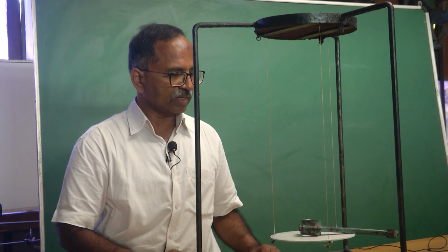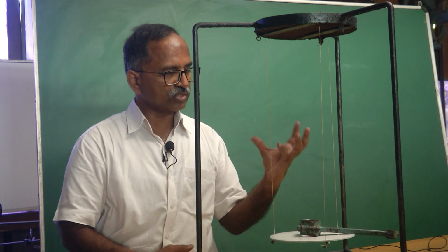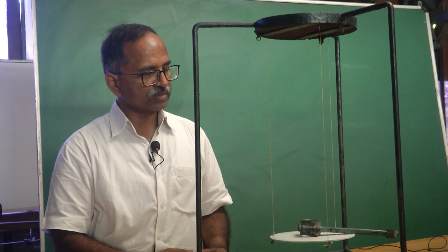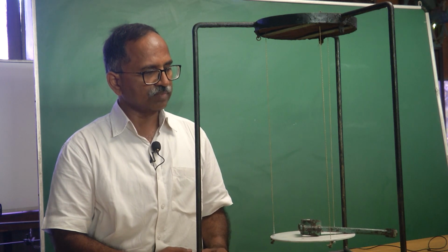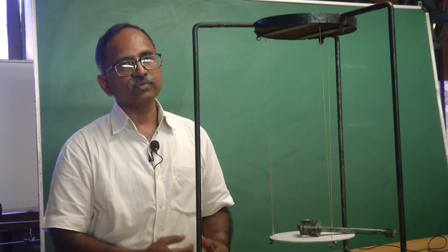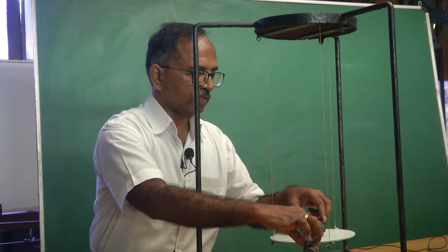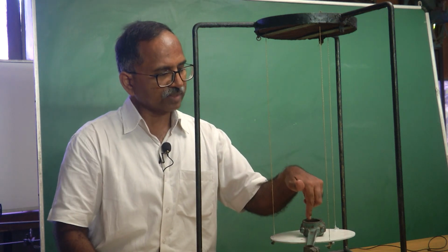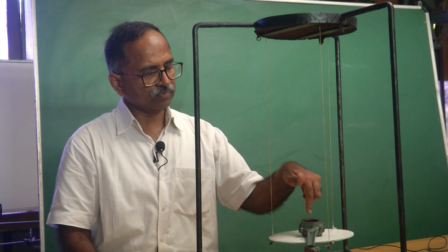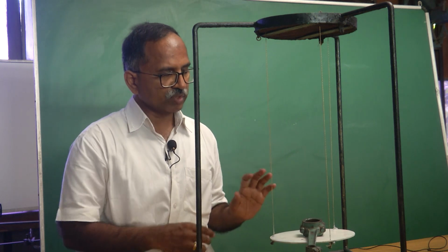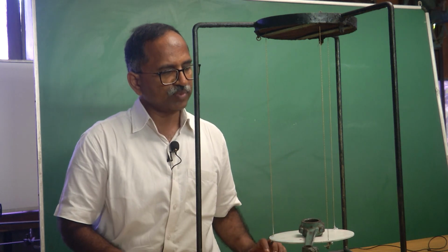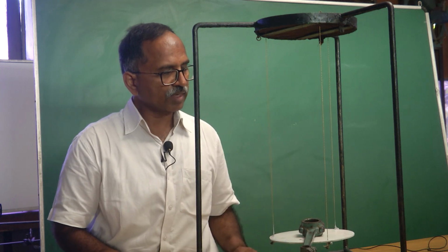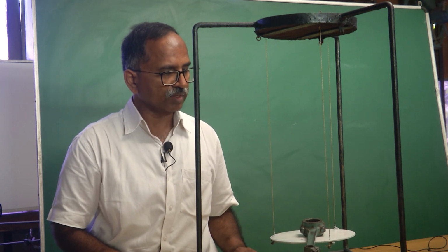And you can notice that the plate is generating an oscillatory motion, and this free vibration response can be recorded and we can find out the period of oscillation. Place the connecting rod with the axis of the plate aligned with that of the big end of the connecting rod, so that whatever value of mass moment of inertia I will get will be about the axis of the big end of the connecting rod.